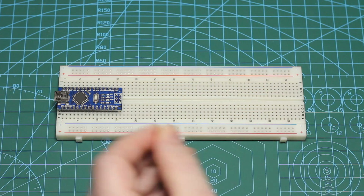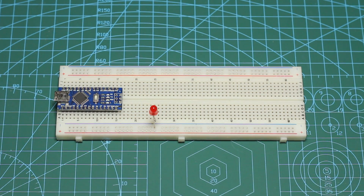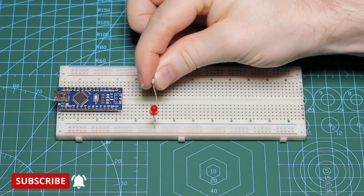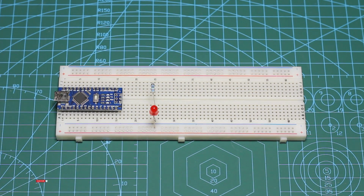Place the negative leg of the LED into the negative rail on the breadboard, and the positive into one of the rows. Now insert one leg of the 240 ohm resistor into the same row as the positive leg of the LED, and the other into a free row.